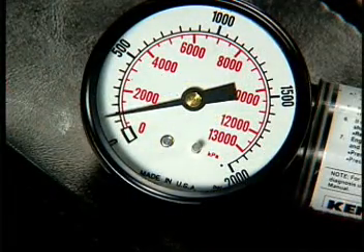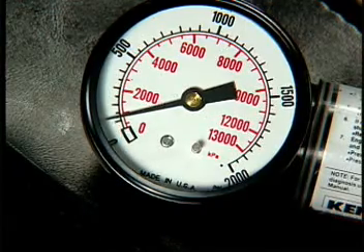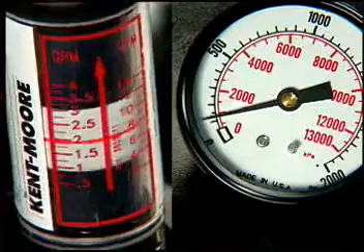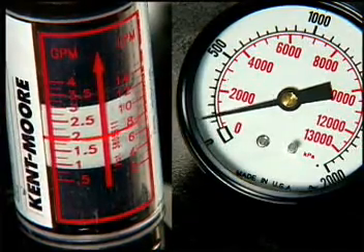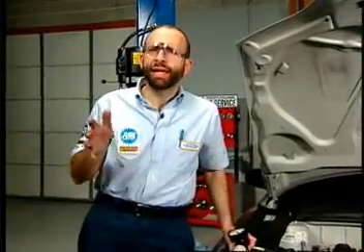At this point, hydraulic pressure should be between 80 and 150 psi, while flow should be almost 2 gallons per minute. If pressure is greater than 150 pounds, look for a kinked hose or other restriction in the system. If flow is less than manufacturer specifications, you may have a faulty pump. In any case, continue with the test.